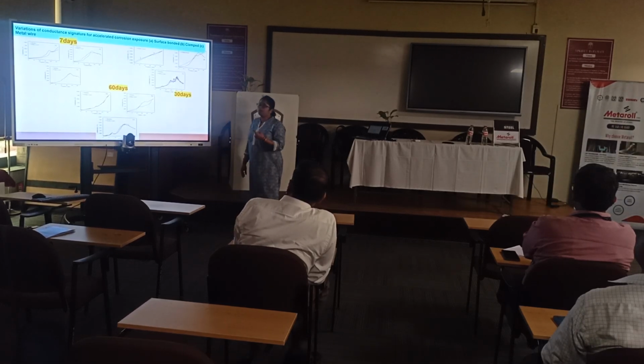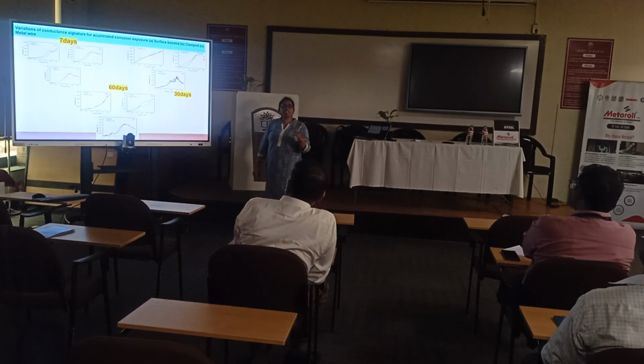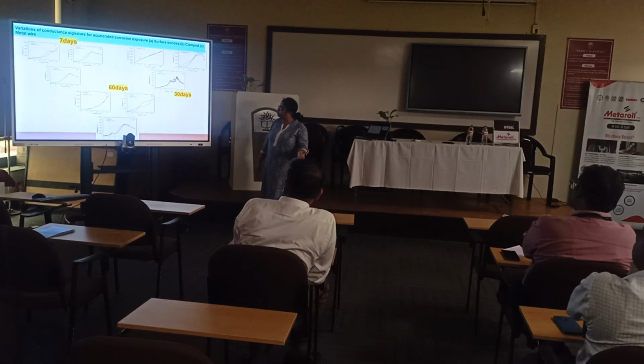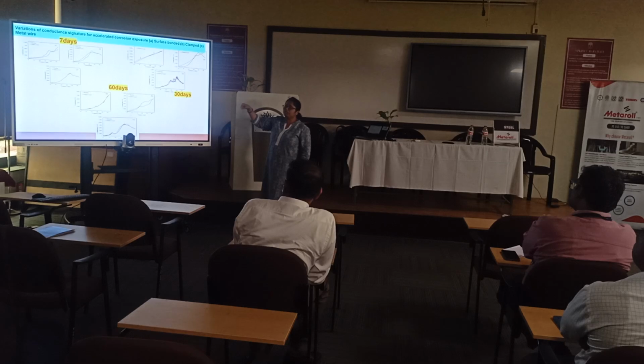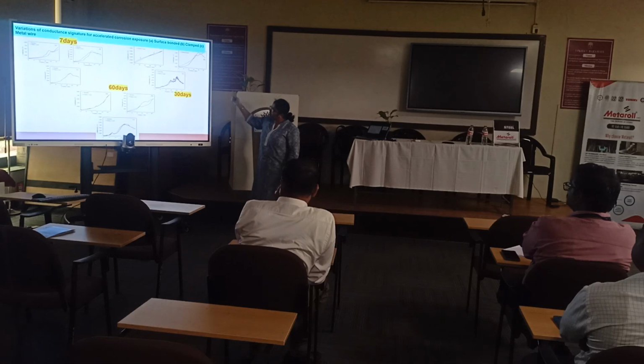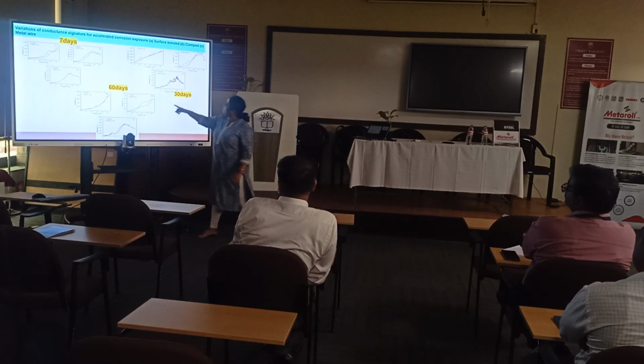That gives you an idea of reuse, that is a reuse configuration, and the non-bonded configuration is more important for such interfacial bond strength monitoring, because anything that happens within the structure, the steel is rusted out. So at 60 days and 30 days, we hardly get any kind of signal, but for the clamp-based and wire-based, we got a very nice one.